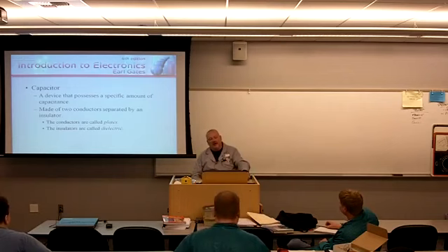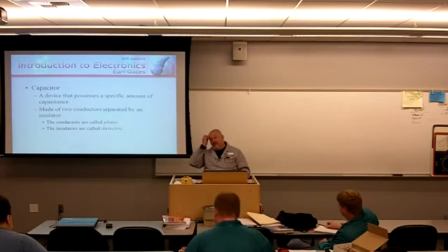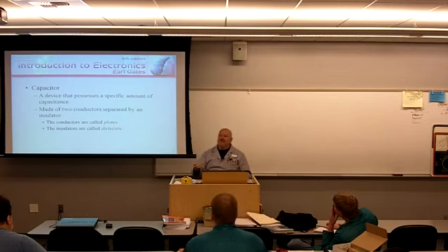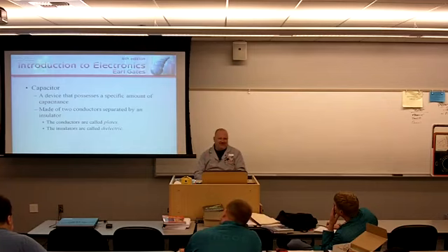Yeah, so you know what? There are going to be a lot of things that have capacitive properties because they're two electrical conductors separated by an insulator. And a lot of these things that have capacitance is stray capacitance and capacitance that we don't necessarily want.